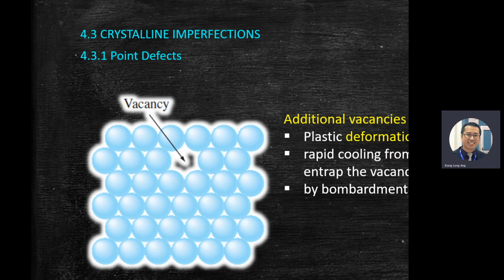Normally, if you do a test, the stress-strain graph, later we learn about this graph. The straight line means you pull and let go, and it returns to the original size. Once it passes the elastic limit, we go to plastic behavior. You pull, it goes back a little bit, but not to the original size, like bubble gum.